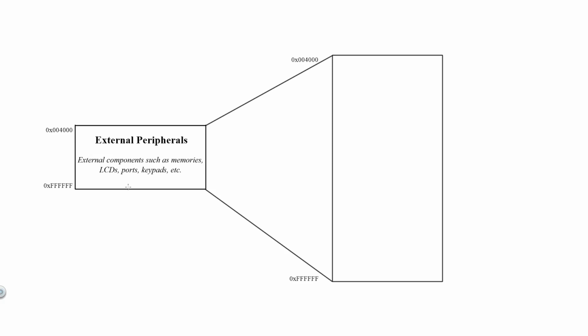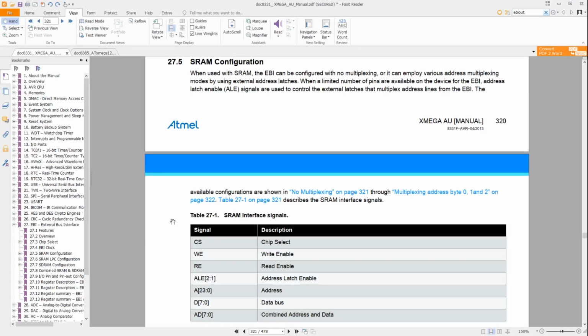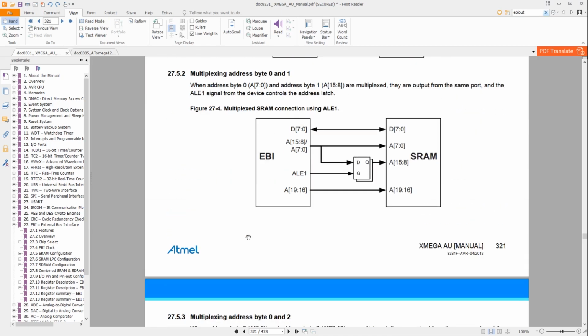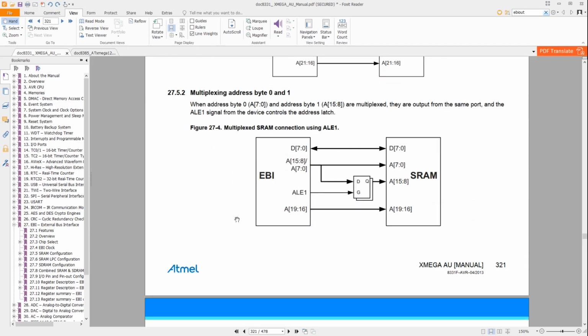When configuring EBI, before deciding where in memory you're going to map your peripherals, you must decide which EBI mode suits your application. In this class, we will always use an SRAM configuration for the external bus interface. This configuration gives us physical access to the address bus, the data bus, as well as all of the control signals necessary for most typical applications that are specific to the MicroPad 2.0 kit. When using the SRAM configuration, there are 4 different arrangements we can choose from in which we can access all of these interface signals. The different arrangements allow us to customize the way we set up the hardware such that it suits our specific application.